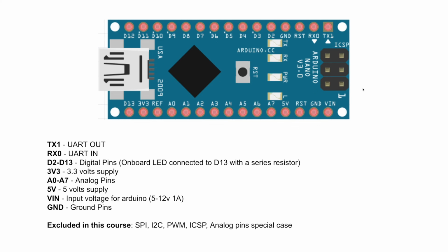Now, you can connect any power supply, but from my experience, I have figured out that any power supply in the range of 5 volts to 12 volts with a current supply of 1 ampere, maximum 1 ampere, is ideal for your Arduino Nano board. If you connect, let's say, a 12 volt 2 ampere power supply to the board, I have experienced in some cases that this microcontroller chip starts to heat up. So this is the ideal range. 5 volt 1 ampere is perfect for your board.